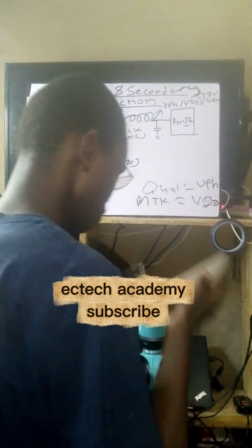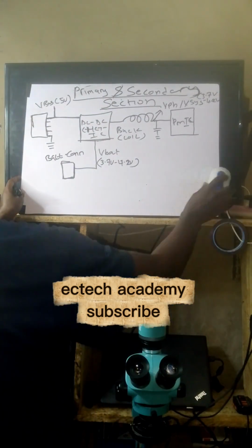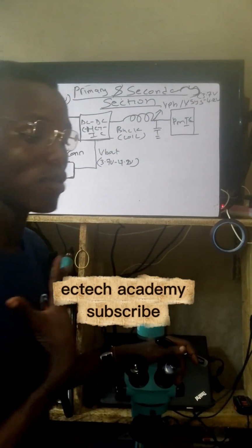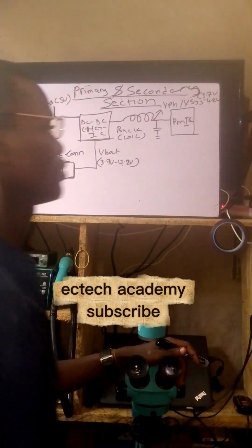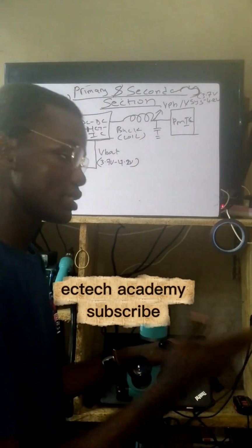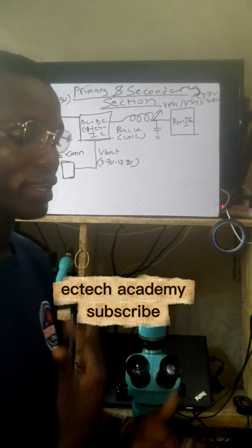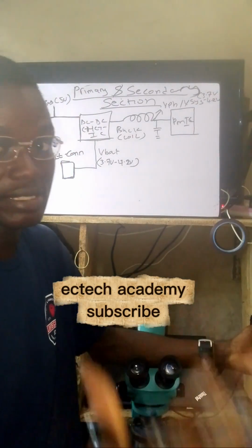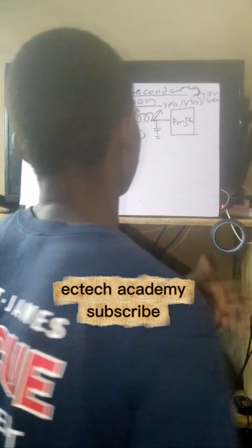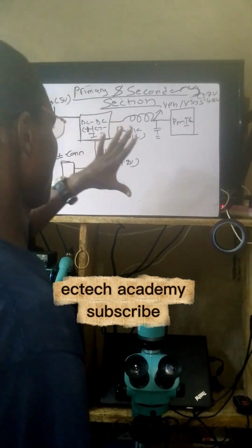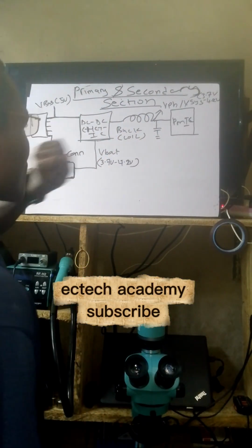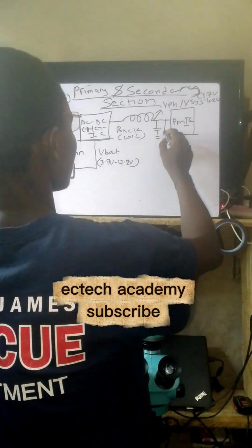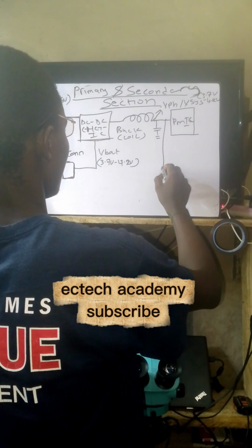So do not be confused. It's just the schematics of the mobile chipset. Mobile chipsets like Qualcomm and MediaTek have their own way of calling things, their own language for calling their signals. When you are studying schematics, you will learn about that. It's the same thing, VPH and VSYS. So let's go into our main topic. Now we have VPH power. We said that this VPH power goes all over to other sections. It goes to some sections.